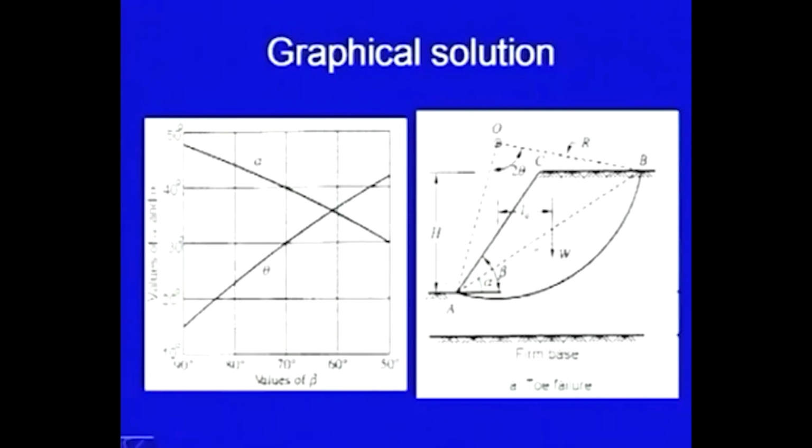This is the example here. So we took this circular surface, and here it is the weight. Its lever arm is L0. This is the center of the circle. This circle we have taken arbitrarily as the first trial circle. This is the radius. So we find out the weight of this wedge and the moment which this weight is trying to generate. And this moment is being resisted by the cohesive forces which are acting all along the periphery of this arc. So if Cm is the cohesion,